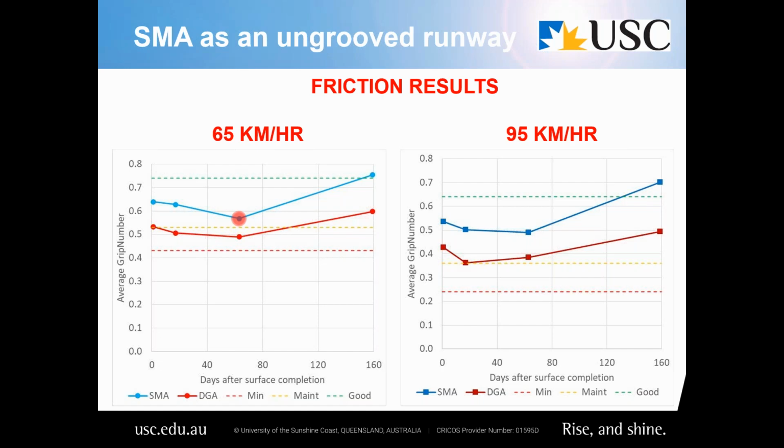But after that, we started to see the bitumen wear off the top of the stones. When we went back after about 3 months, we were off the chart in terms of friction. In fact, the friction testing technician said those were the highest values of friction he'd ever tested on a runway. And of course, not grooved.